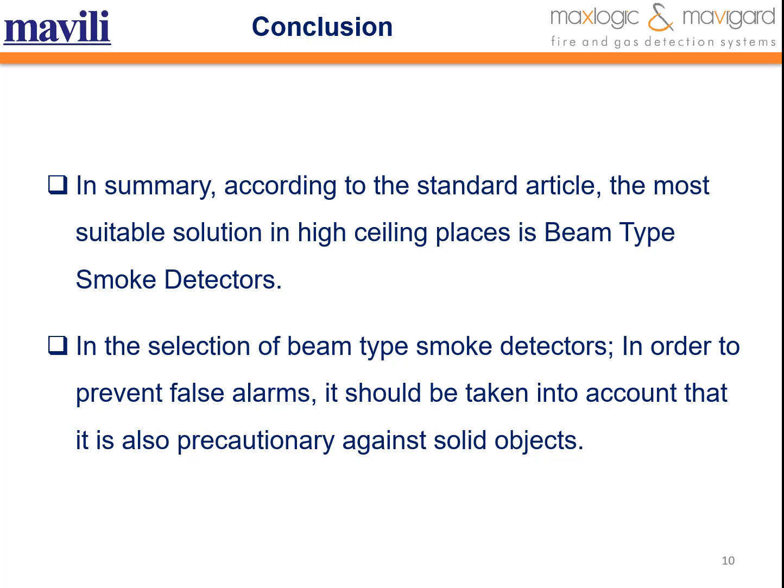As a conclusion, according to the standard article, the most suitable solution in high ceiling places is beam type smoke detectors. Due to its particle structure, smoke blocks the rays by a certain percentage. When a solid object enters between the receiver and transmitter, the beam exchange is prevented by 90 to 100%.